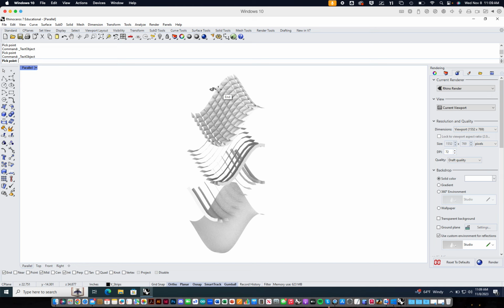If you want. But at the same time, you can either do Make 2D and then manually manipulate line weights in Illustrator, or you can go to the display viewport settings and, similarly to what we did in Production 1, make your own viewport mode, a combination of the technical mode with the rendered mode or Arctic mode or whatever you like, where you get tone and soft shadows, but you also get line work. You can set things like the silhouette line weights versus the edge line weights. Okay, makes sense? All right, good.